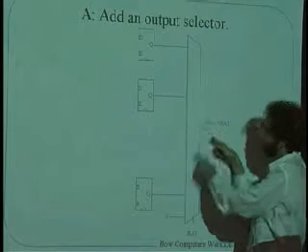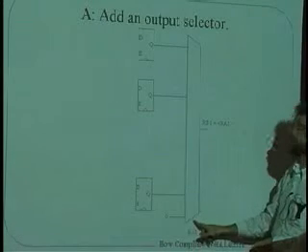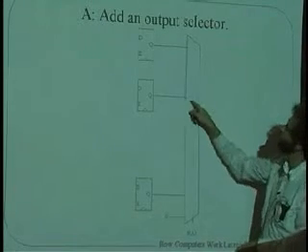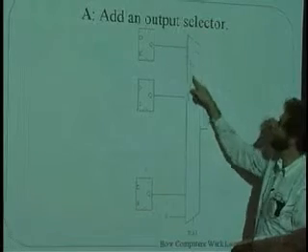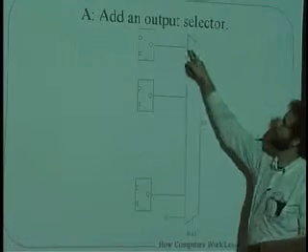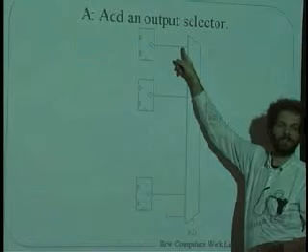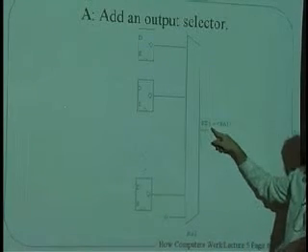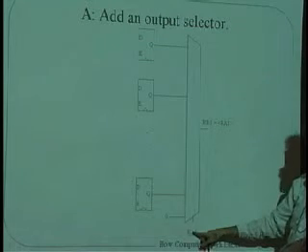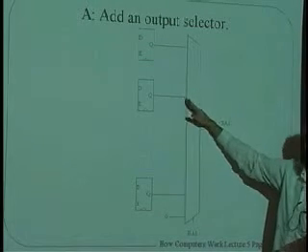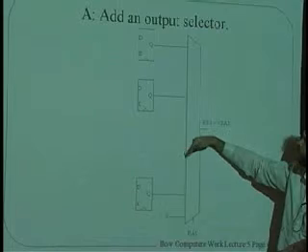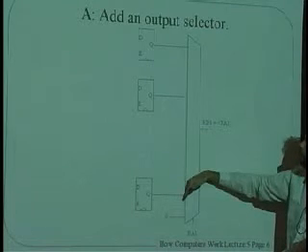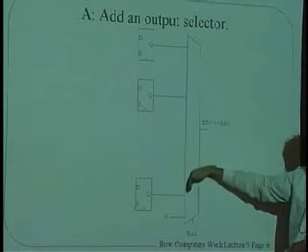If we wanted R0, we would put a 0 into here, and the selector would choose, we'd draw a red line between here and here, saying that we're going to choose the output of this guy up here, all 32 bits of it, to get steered down to here and come out. On the other hand, if we put a 1 into here, we're going to choose this one. A 2, we'll choose this one, 3, 4, 5, 6, 7, all the way down to register 30 down here.